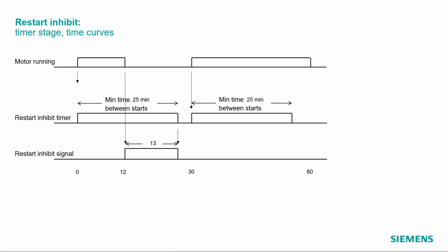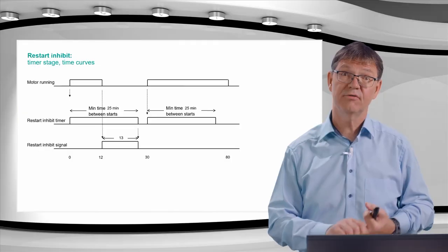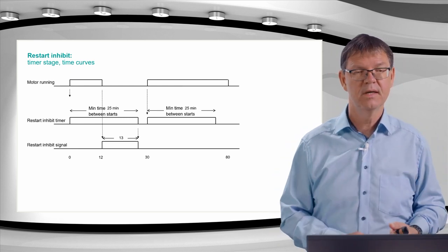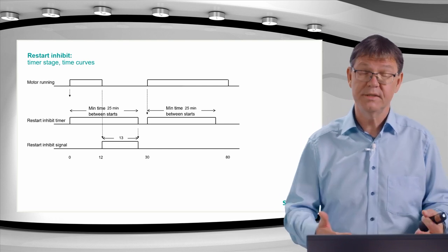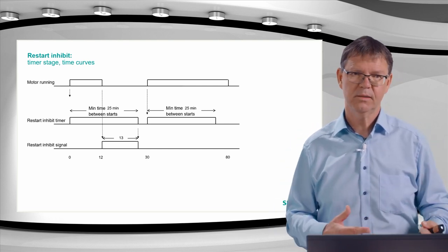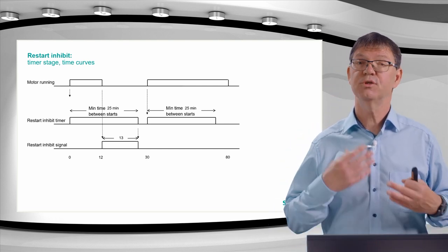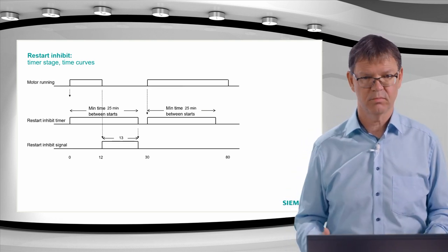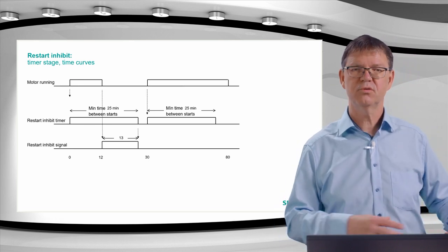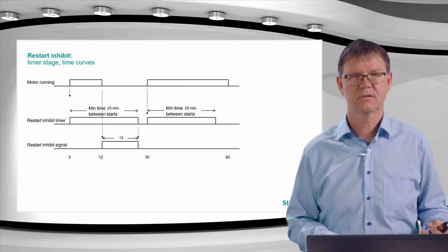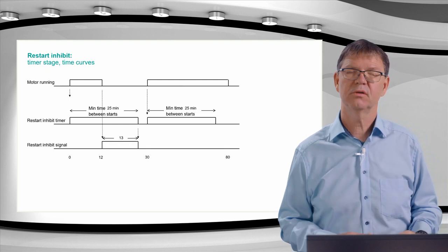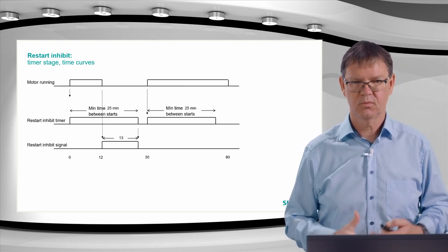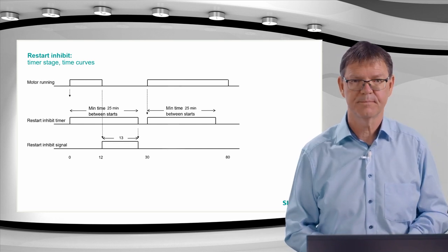Okay, again, this timer and counter stage is for if you have additional data from the motor manufacturer that goes in that direction, then you can apply these stages, activate these stages. It's an additional help. I would say in addition to the thermal stage, if you have the data for the thermal stage. Okay, this is the recommendation. You can do what you want. You don't need to use one of these functions or one special one of these functions. It's up to you at the end. So what we can do is to offer all these principles here.